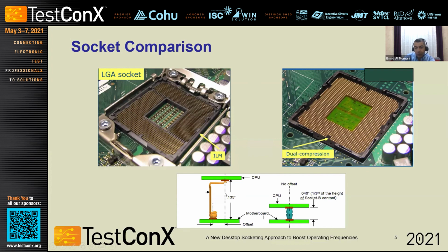Height is almost 3.2 millimeter. And one major thing to notice is the offset that you are seeing between the socket, basically the package pad, and the PCB pad. This cantilever design forces this offset to happen; we need this offset to be there. And going to the right, here is an image of an elastomer socket, one of the technologies that we're going to be talking about today.